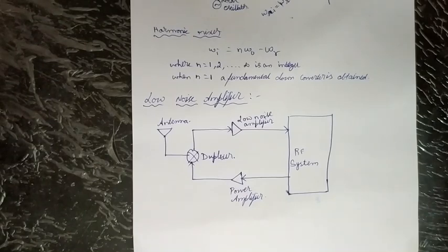The primary parameters for low noise amplifiers are noise figure, gain and non-linearity. The noise is due to thermal and other sources, with a typical noise figure of 0.5 to 1.5 dB range. So the noise figure helps determine the frequencies of particular low noise amplifiers. A low noise figure results in better signal reception, and must come with a high gain. Typical gain is between 10 to 20 dB for a single stage.